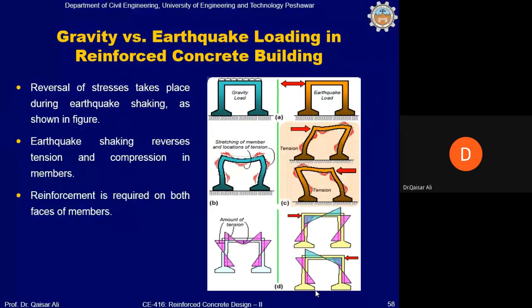Another point is that these walls have openings. The walls are usually not too thick. They are thin walls in order to reduce the load on them. So up to this extent, we can say that if these walls exist in reinforced concrete frame elements, only transferring their load to the beam will not be sufficient. They must be modeled properly in the numerical models. Okay, sir. Thank you, sir. Any other question?